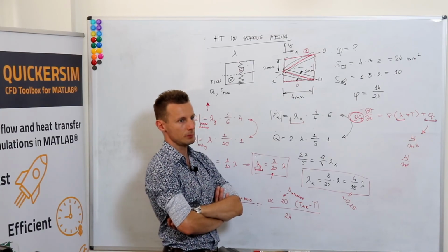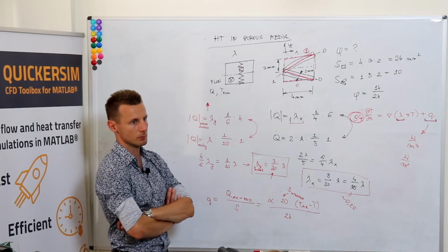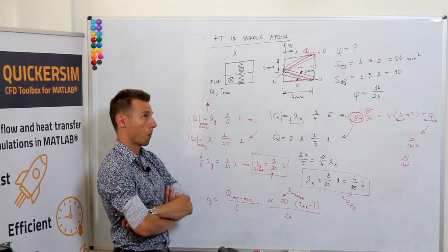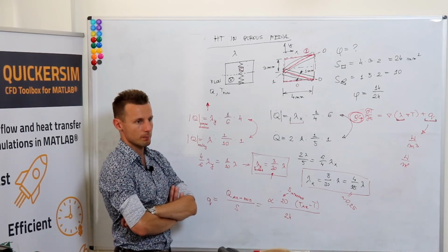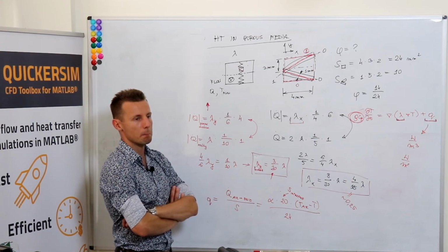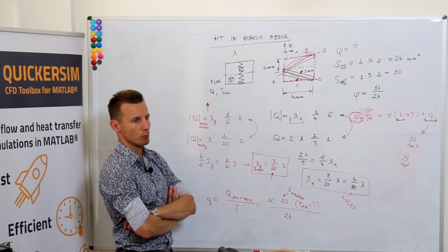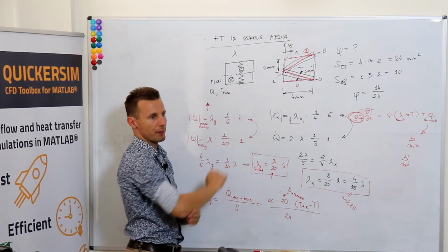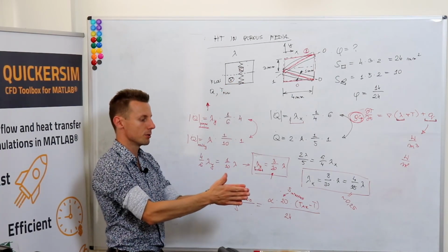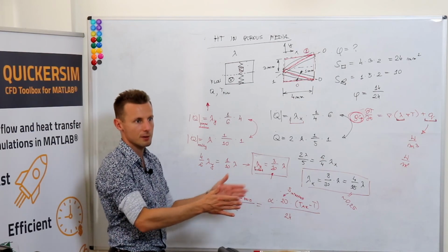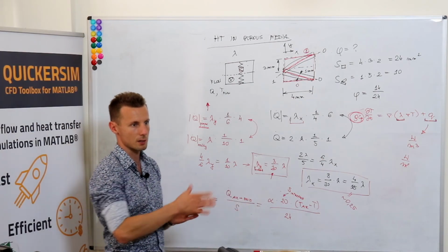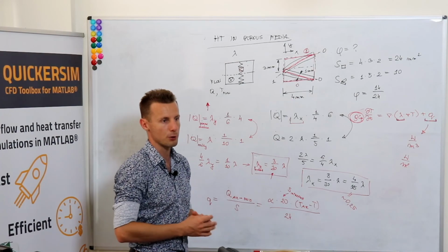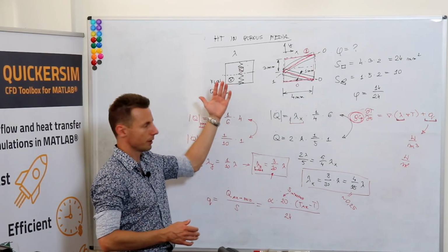If it's not, then probably we would need to take a logarithmic difference, like in a heat exchanger equation, solve a nonlinear equation, and we'll get the solution anyway. Or what you would maybe do is you would say, okay, it has got some depth in the other direction, and you need to still discretize the depth to account for this temperature variation along the flow.